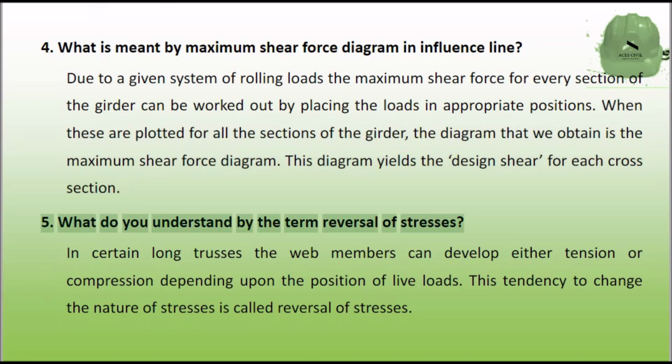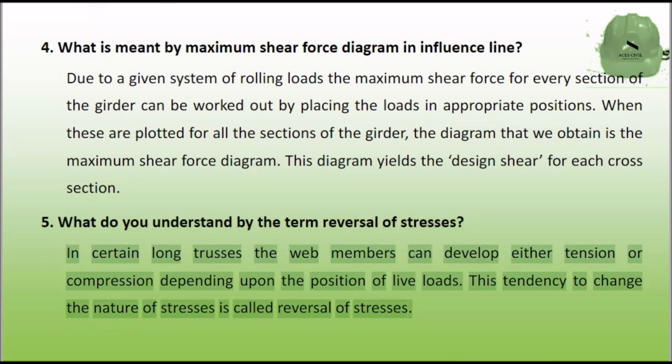5. What do you understand by the term reversal of stresses? In certain long trusses the web members can develop either tension or compression depending upon the position of live loads. This tendency to change the nature of stresses is called reversal of stresses.